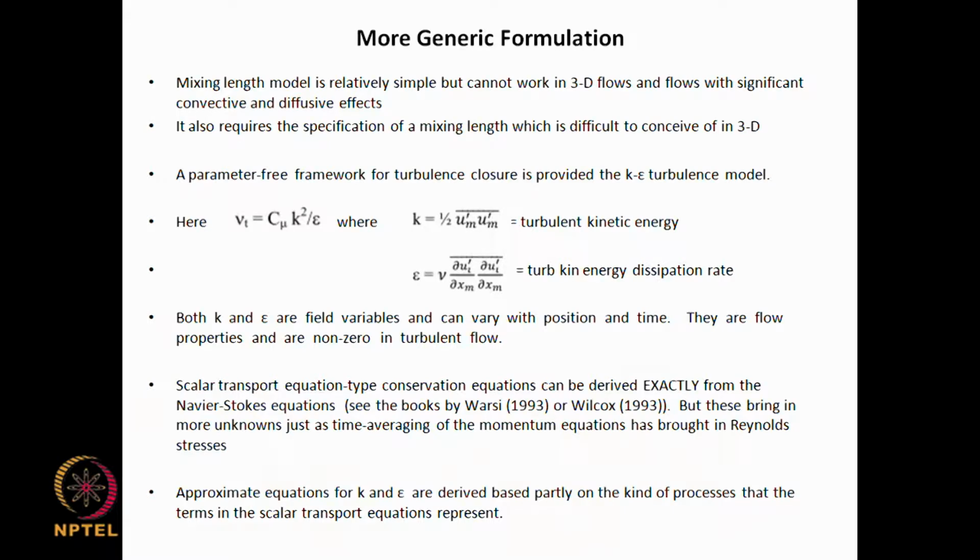If you are looking at turbulent flow, then immediately one would say k-epsilon model. This model has gone through some transformations and further developments, and various kinds of k-epsilon models have been developed, but the basic idea is that turbulence is characterized by two quantities, the turbulent kinetic energy and the turbulent kinetic energy dissipation rate. These can be mathematically defined, and that is what we have here.